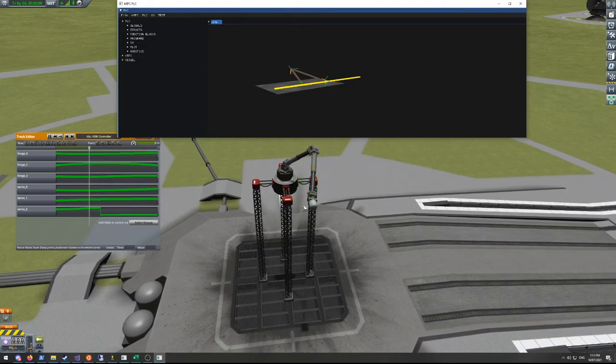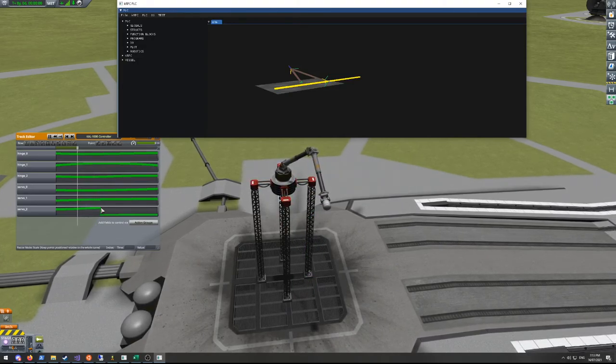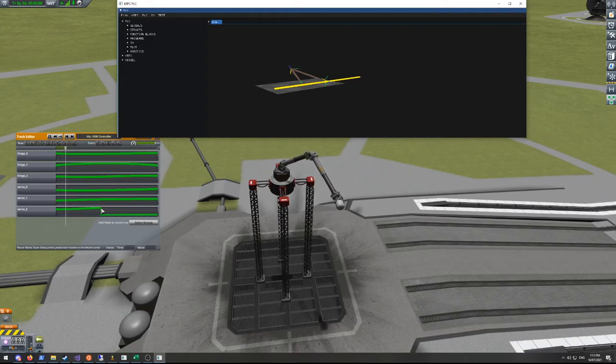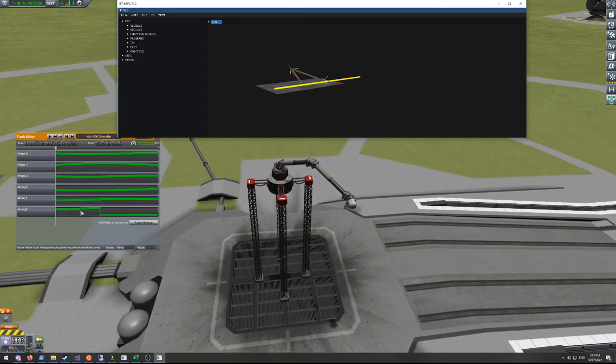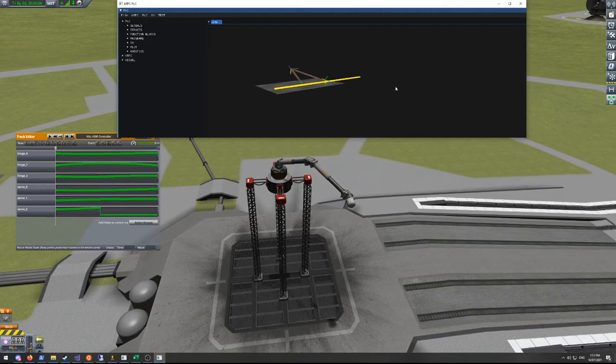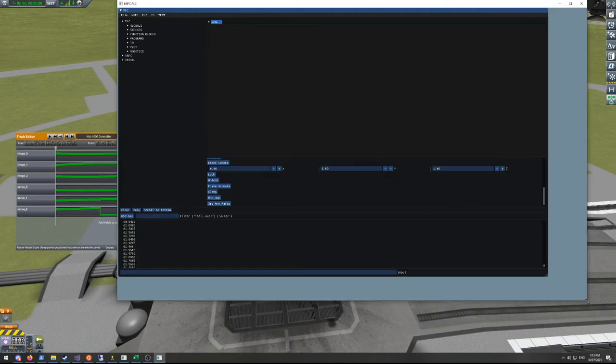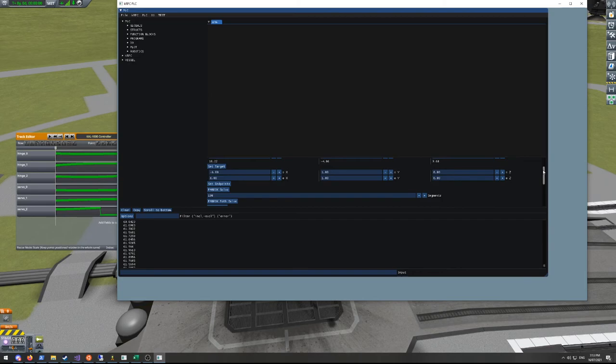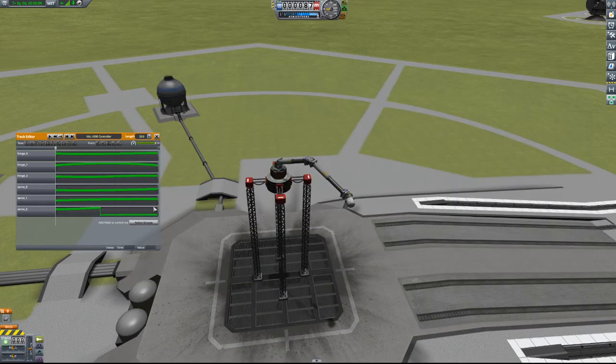You can see it does a little wobble there because it's switching from one end to the other with the servo at the end. So that's why we use a lot of segments on the calculation, so 100 in this case, to avoid it snapping and flying around, trying to rotate all the way back around the other way to get to the target. And that's also why you drop the traverse rate right down low, so that even if it tries, it can't get there very quickly, so it's not going to snap around or anything.